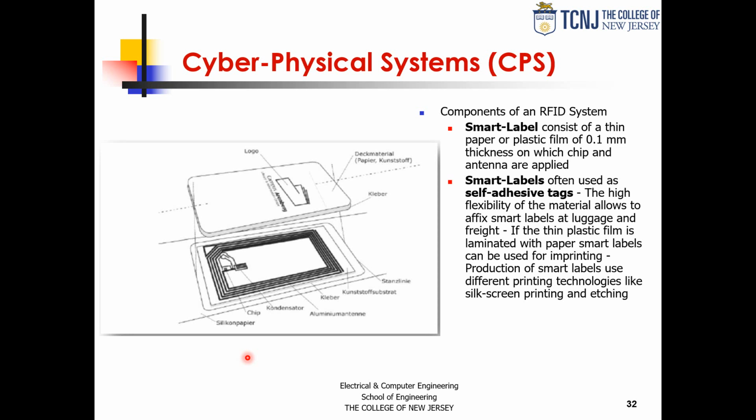But again, you can print a lot of these structures on plastic or paper with some type of copper silver alloy. And you can print it with very, very fine resolution. It's really the same technology as inkjet, but instead of ink, you have a solution of copper silver that you keep warm or molten, and then when you deposit it, it cools and hardens, and then you have something that you have printed.